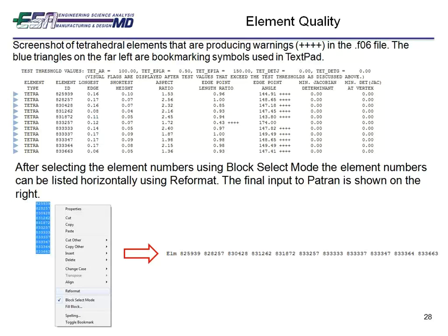So you can quickly go from that list of failing elements in Nastran back into Patran, and you can easily see where you're having issues with your elements. I've also used this pretty effectively for looking for other results, and it saves a lot of time rather than scanning manually through the F06.